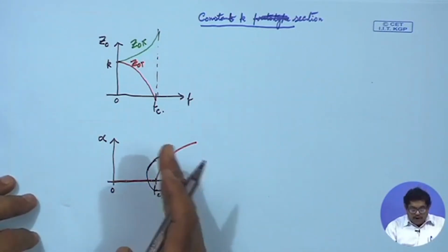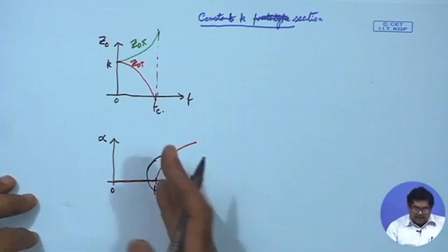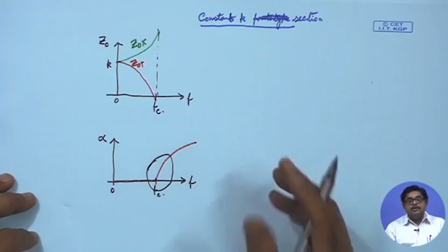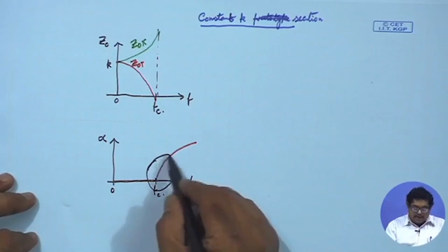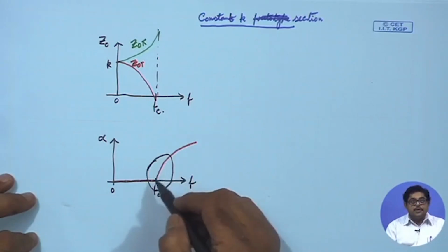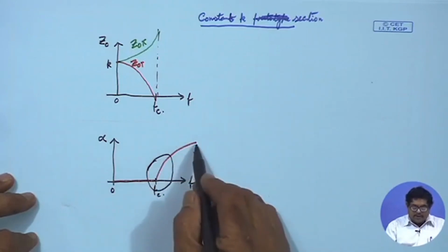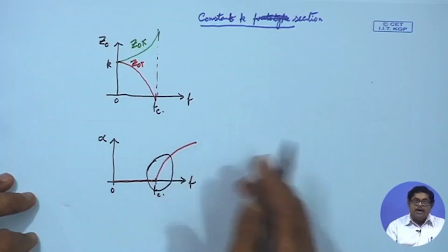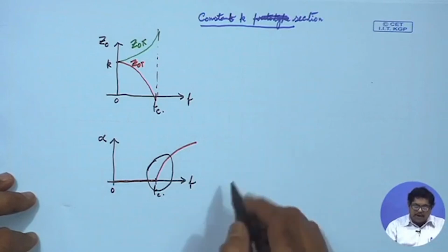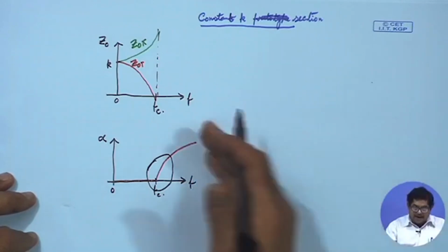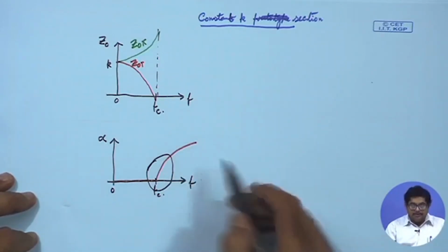So, if I have another channel or radio signal very near to the cutoff frequency, the attenuation will not be much. Once it is separated by a reasonable distance, it goes to a high value, and it is also desirable that when omega is very high, the attenuation is infinite.